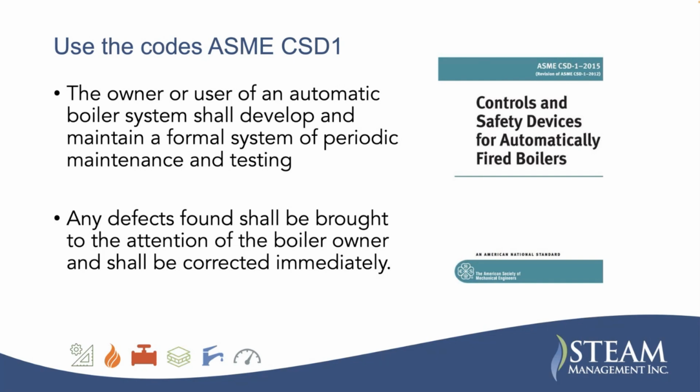But it says the owner or user of an automatic boiler system shall develop and maintain a formal system of periodic maintenance and testing. Any defects found shall be brought to the attention of the boiler owner and shall be corrected immediately. Now, what that does is that lets your service technicians off the hook because they say, hey, this thing needs to be done. And if you present the code to the owner, it's not you telling them it has to be done, it's the code saying it. So it makes it easier. Sometimes technicians get a little intimidated by building owners.